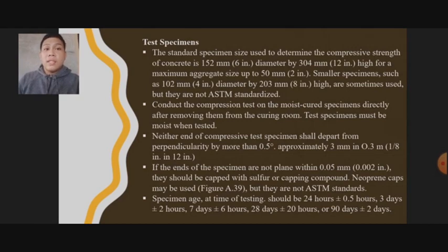Next, conduct the compression test on the moist cured specimen directly after removing them from the curing room. Test specimens must be moist when tested.